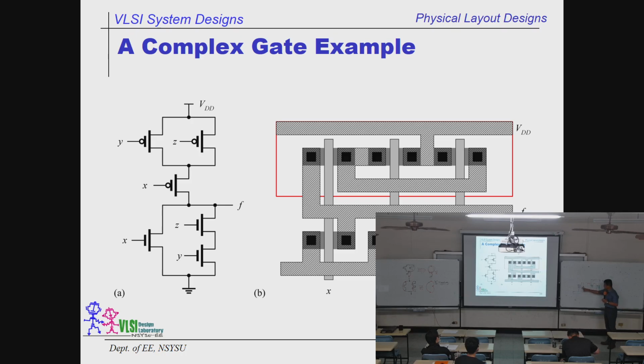So this is for the P design. See, single piece. And you see how stupid that is? See that difference? This example shows you that if you don't follow the Euler path, you sacrifice a lot of space over here. Because this is a short circuit, basically you can use a single diffusion to short them together.